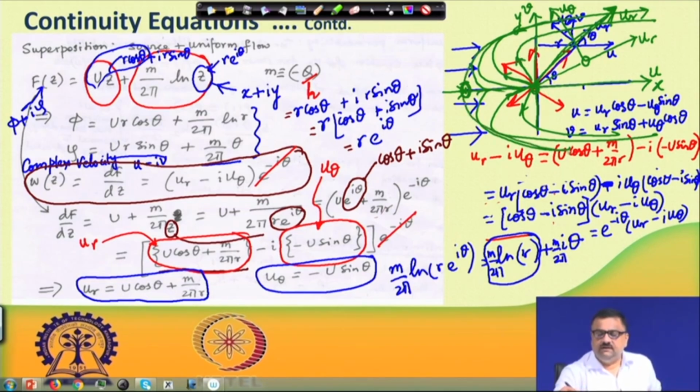At this point, the radial flow that is coming from the right and the uniform flow that is coming from the left, these two streamlines will hit each other and the fluid becomes static here. This point is referred to as the stagnation point. Intuitively I can see there would be a stagnation point and an envelope. All the radial flow that I am putting in here would be enclosed in an envelope because of this uniform flow that is coming from the left.